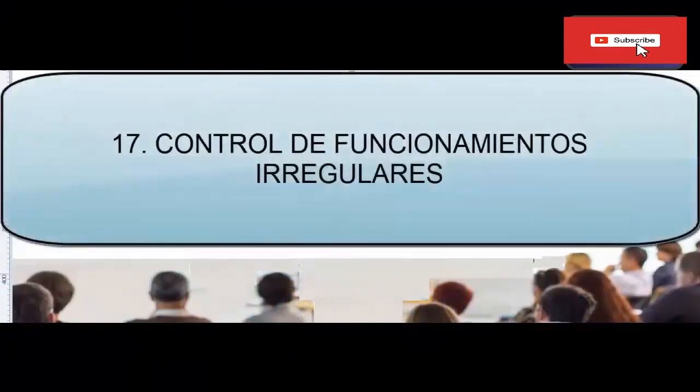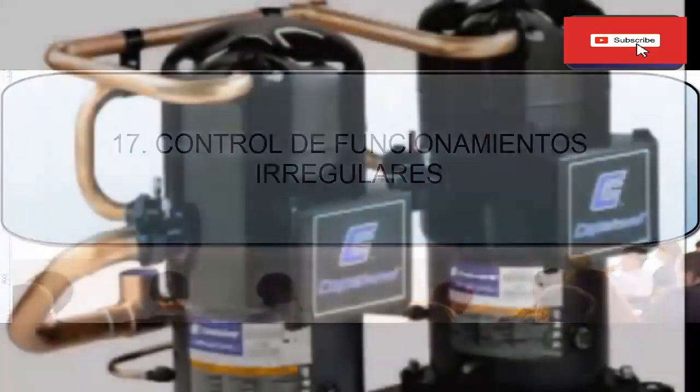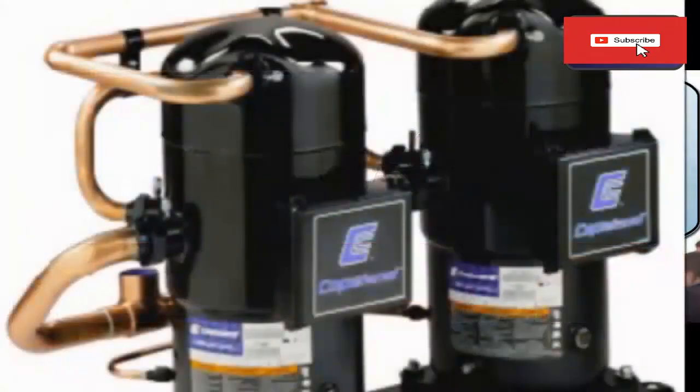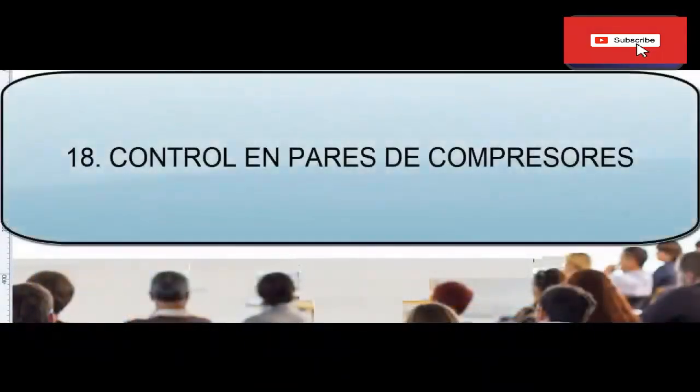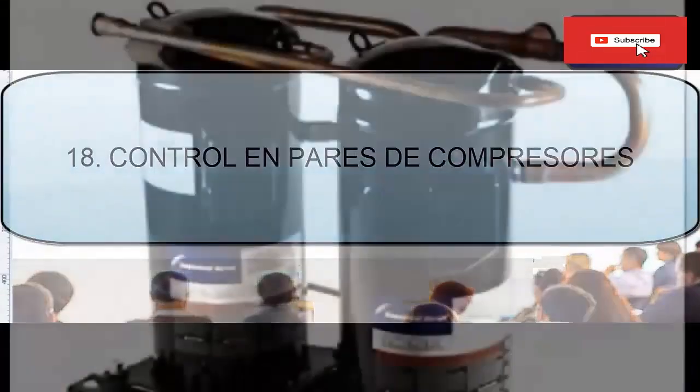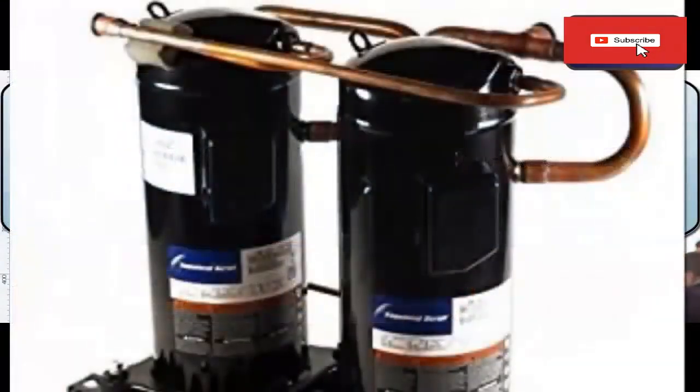An electronic evaporator controller is also used to prevent system malfunctions. You can set the time that the compressor can be running once started and the minimum time that it must remain stopped.